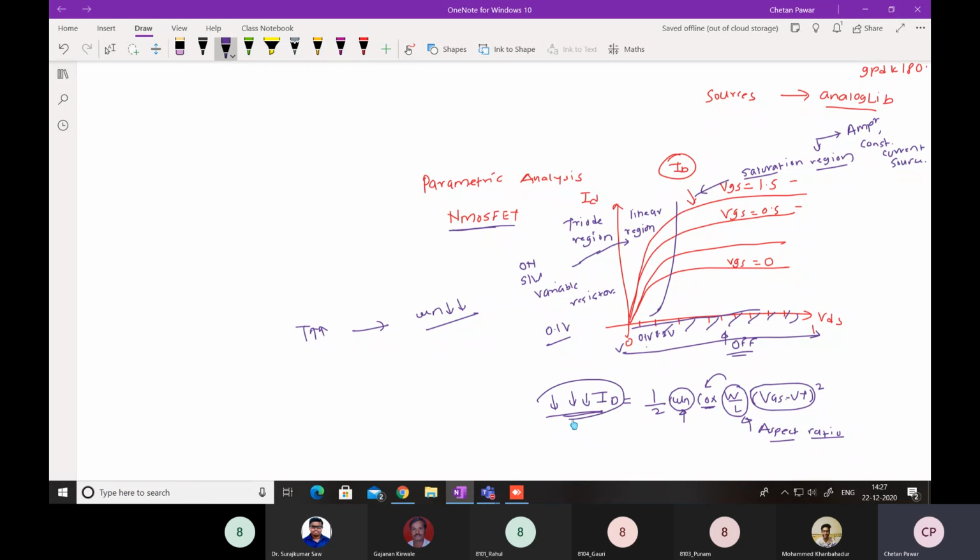So if the drain current changes, for example, if there is one amplifier, as you know, for an amplifier, biasing is required to keep the operating point in a particular region. Suppose I want to operate the MOSFET in this region to use it as a constant current source, I need to put the operating point into this region, right? So I need to bias this amplifier properly.